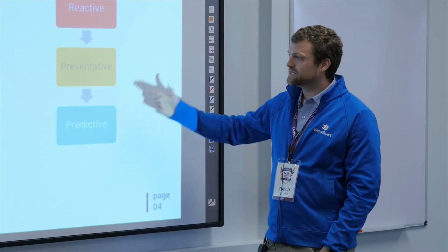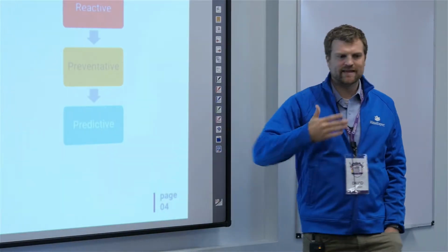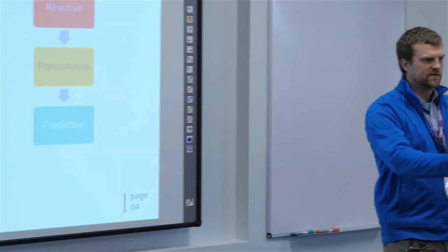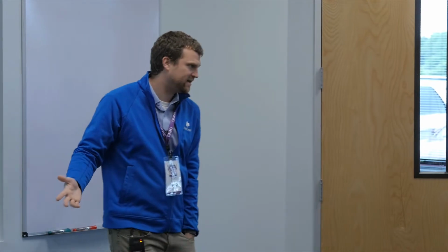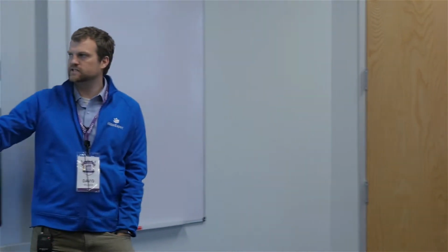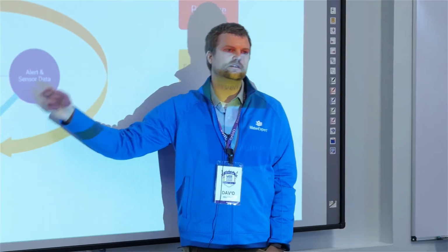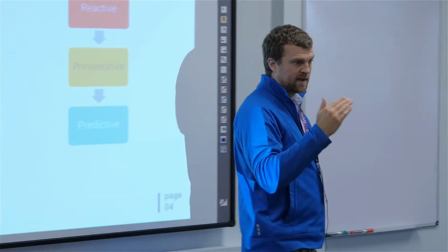Next one is predictive. So it's one thing to say 500 hours in our manual that we give you, right? We all know that your plant's different from your plant's different from your plant, right? So that 500 hours may or may not be the right number of hours. But if your maintenance is hooked up to your equipment, and these two are talking to each other, you can say, if my motor ramps up too hot, or my level gets too high, I need to go maintain, right?